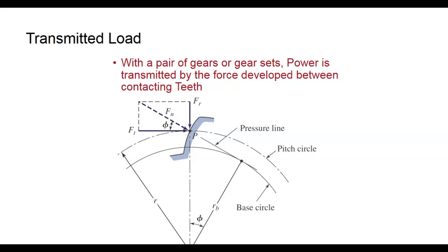A lot of times on the gears, if you ever notice, the actual teeth will come up and then it'll angle, and then it'll be like this. And when it meshes, it won't go all the way down into the thing. Or they'll deliberately have a space in here. That's what I've seen. And of course, you can see why they angle them like this on the top, right? Because it makes the transfer when it moves in and out a lot smoother.